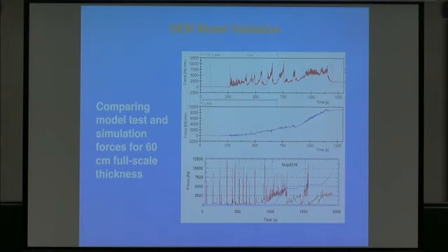You notice it drops to 0 between them because the buckling's occurring way out in front of the structure. Once it buckles, you're just pretty much decoupled for a second. Whereas in the 3D physical model test, you've got a little buckling over here, but you've still got force transferred through the rest of the sheet. Then you have a buckling event over here, but you've still got force through this part of the sheet. So you never see it drop to 0.